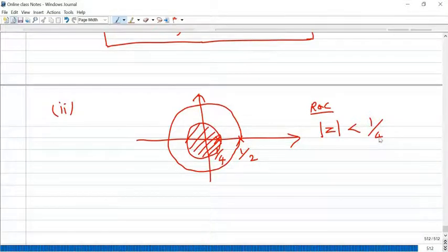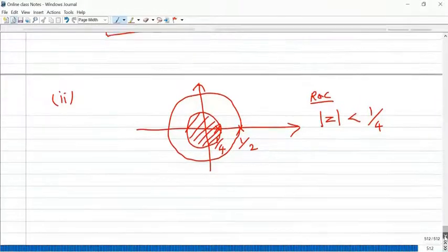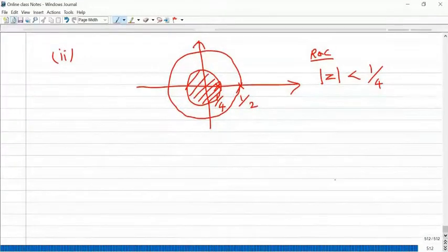Okay. So already we discussed in the beginning of the Z transform, for a causal signal the ROC is always outside of the outermost circle. If there is more than one pole, for a non-causal signal, the ROC lies inside of the innermost pole. Okay. Now your result is,